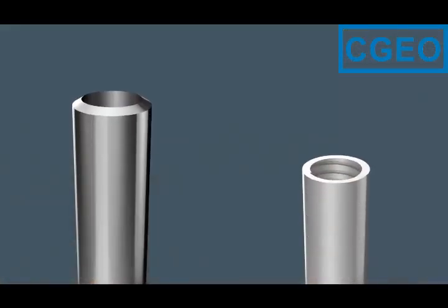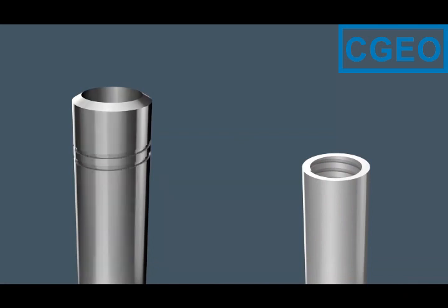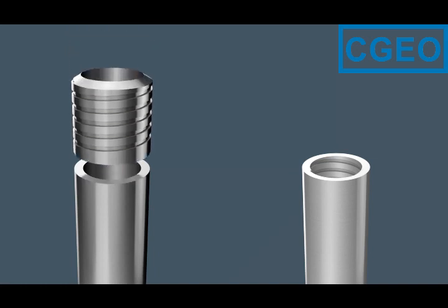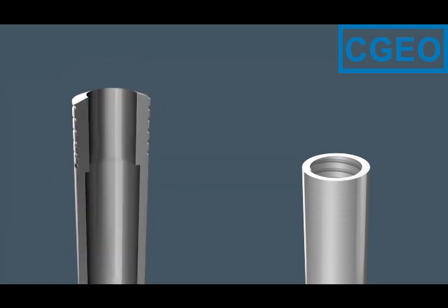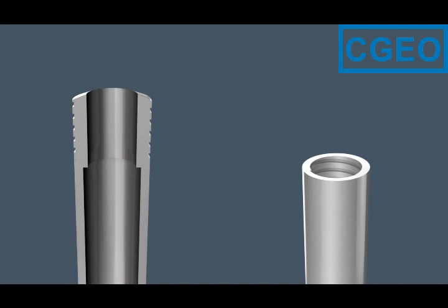Conventional drill rods are made out of steel or aluminum. The steel drill rods are equipped with steel couplings, which are threaded and heat treated or friction welded to the steel body and then heat treated. Since no inner tube needs to pass through the drill string, one dimension of conventional steel drill rods can be used for 2 or 3 core barrel dimensions.